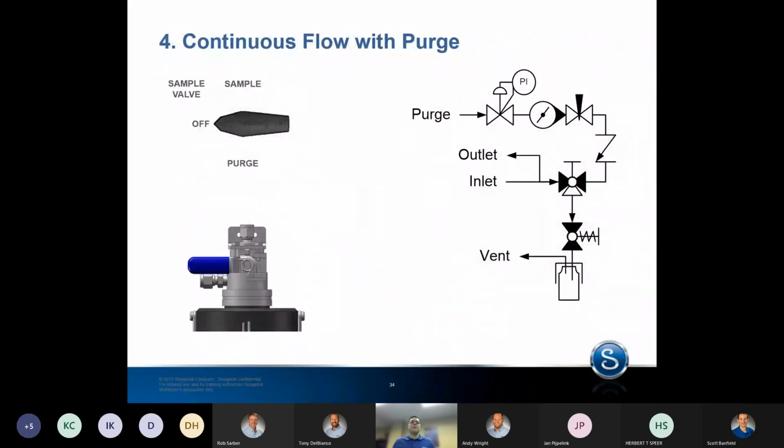So what you see here is the valve in the upper left corner, that's our sample valve. That's going to be the main valve that you're actuating to control the function of the panel. Down below that is the spring-loaded deadman handle that's on the MBS sampler. Your sample bottle is inserted into the shroud below that, and that's ultimately controlling when the sample can flow through your sample vessel. And on the right half of your screen is an interactive P&ID that will have some bubbles flowing through to show you how it operates as you sequence valves.